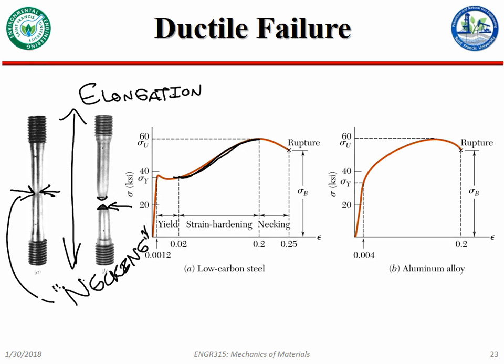So I'll have a micrograph later on. But based on how you work that material and how you stretch it, you strain it, those grains start to reorder themselves. They slip a little bit. They deform, and it changes the characteristics of the material, and you get a different stress-strain response. The elastic modulus, interestingly enough, stays the same, but the response of the material becomes different, if that makes sense.